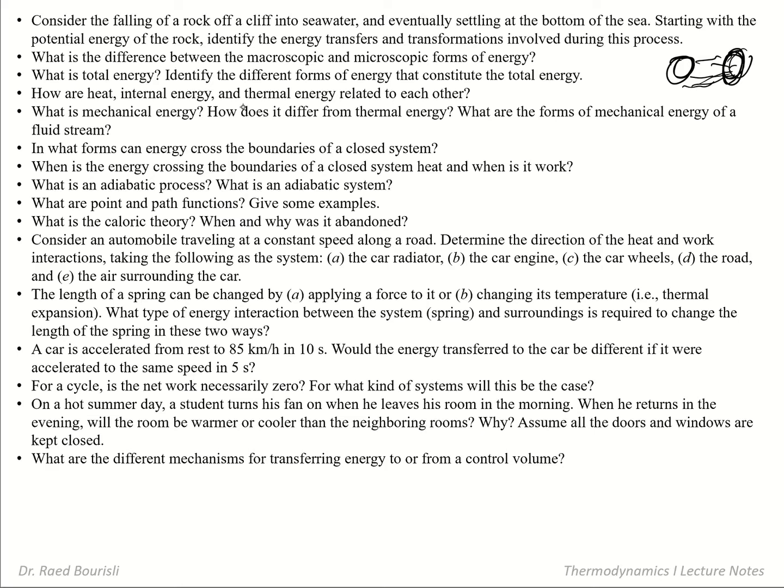Then it says, what is mechanical energy? It's the part of the total energy that can be transported or transformed easily into mechanical work. So that includes, of course, kinetic and potential energy, as well as the mechanical energy contained in a pressure differential between the system and its surroundings.